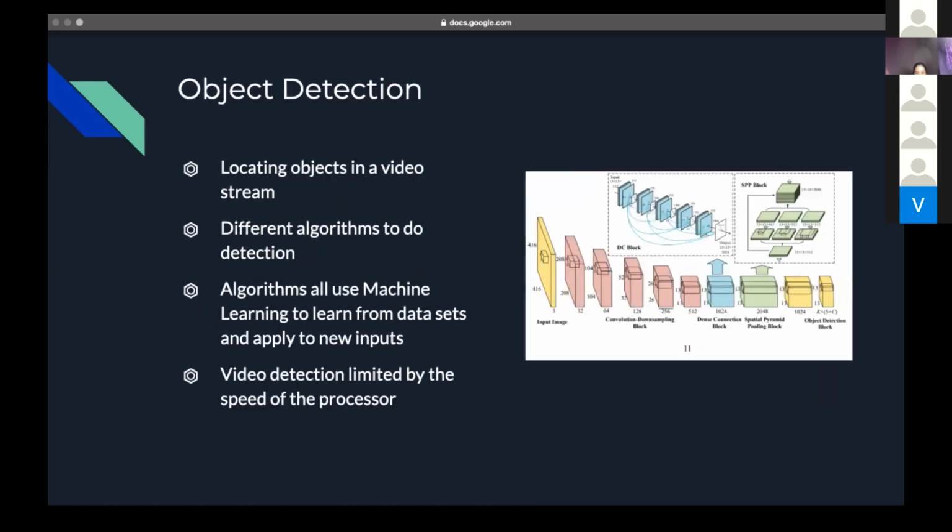What we wanted to discover for this internship was how object detection really works. For us to attempt to implement it into an FPGA, we needed to know the software side really well. For detection, images are fed through a neural network which has multiple layers. Each layer manipulates the data based on an algorithm and results in an output of where to graph bounding boxes around the detected object. The speed of this process is decided by how fast our hardware can finish one image. Processing video requires taking time in each frame of video and passing it through the neural network. Next slide, please.